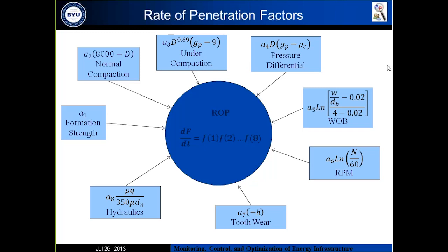So far, researchers have shown the pressure as an environmental variable, but we will consider it as a control variable also here. So it depends on the downhole pressure, and ROP also depends on the weight on the drilling bit and the rotation speed of the drilling string, and also torque. And so these three will be our control variables.